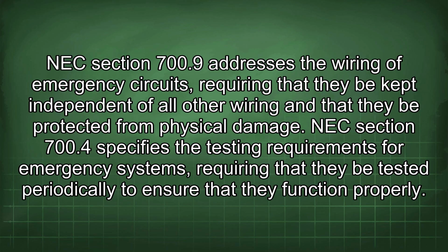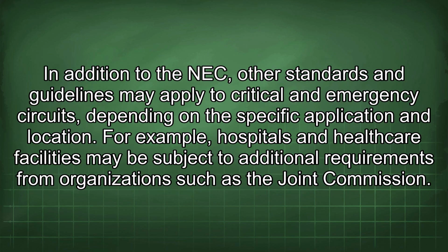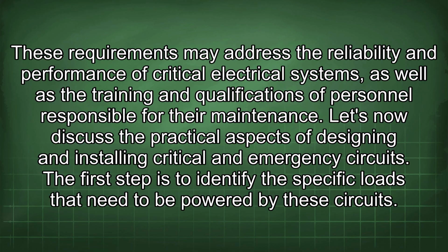NEC Section 700.4 specifies the testing requirements for emergency systems, requiring that they be tested periodically to ensure that they function properly. In addition to the NEC, other standards and guidelines may apply to critical and emergency circuits, depending on the specific application and location. For example, hospitals and healthcare facilities may be subject to additional requirements from organizations such as the Joint Commission. These requirements may address the reliability and performance of critical electrical systems, as well as the training and qualifications of personnel responsible for their maintenance.